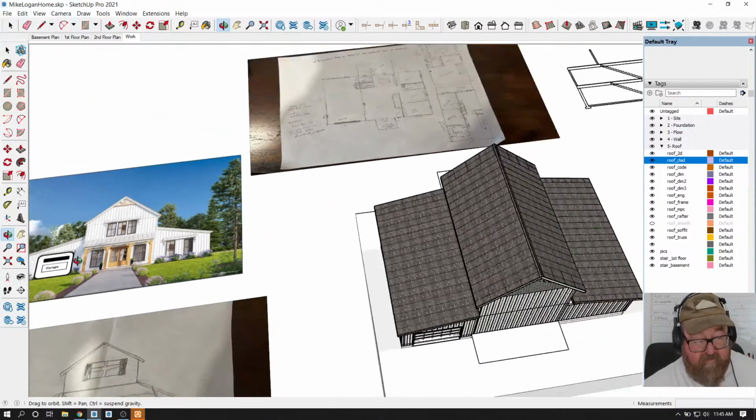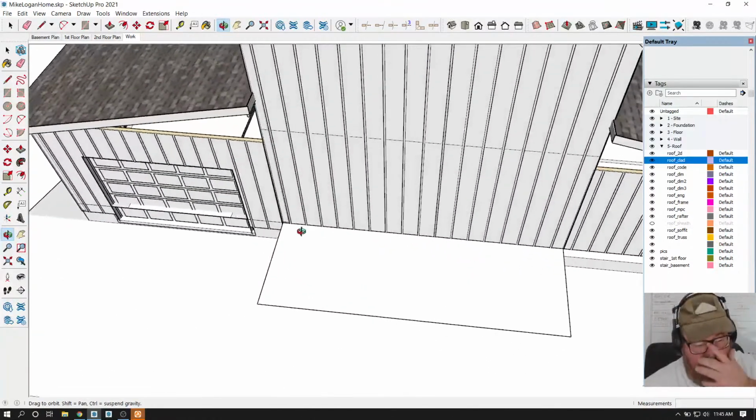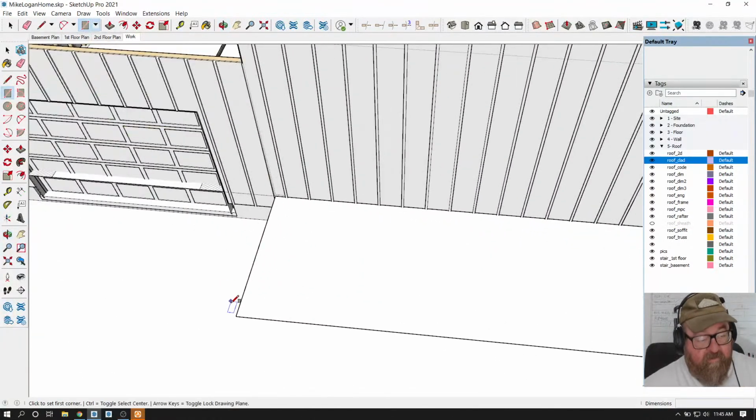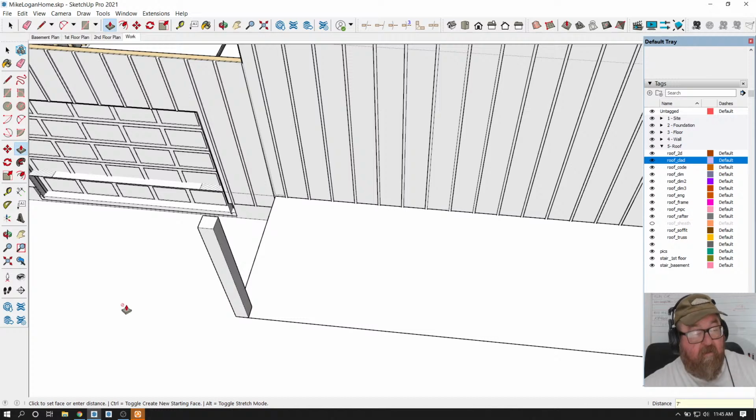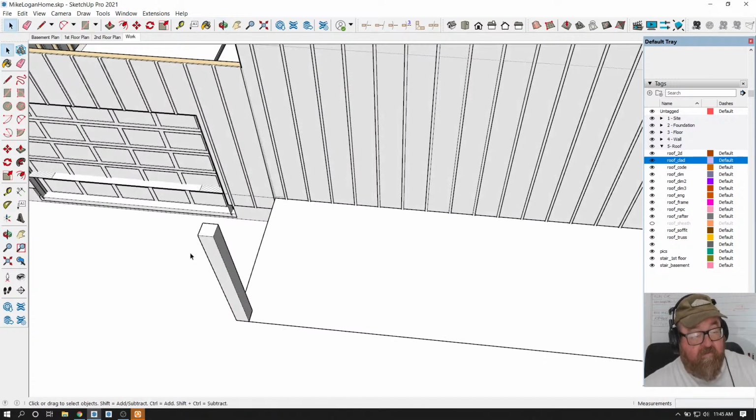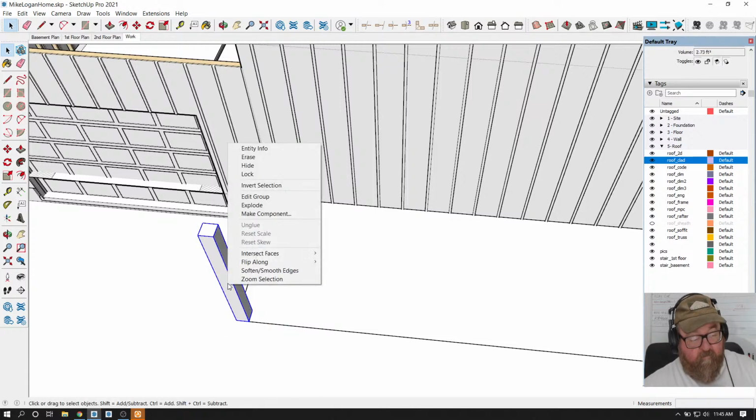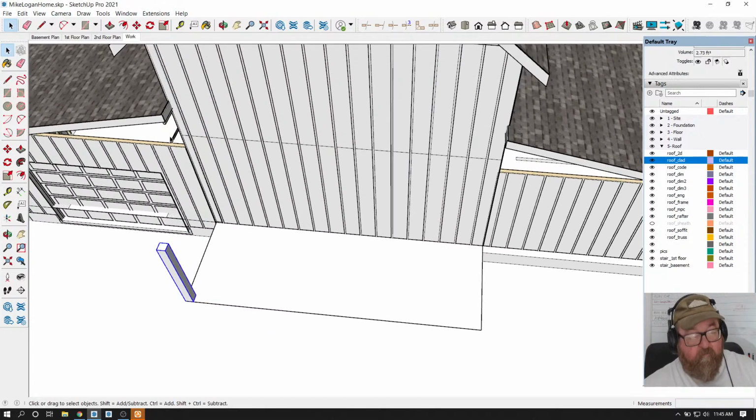And so let's put ourselves just a simple set of columns out here. I think we will use 8x8s. So 7.5 by 7.5. And I usually make those 7 feet tall at least. But I'll make them a component so I can change them. Let's see, 3. Let's see, divided by 3. Let's see, 4. I should have said 3.